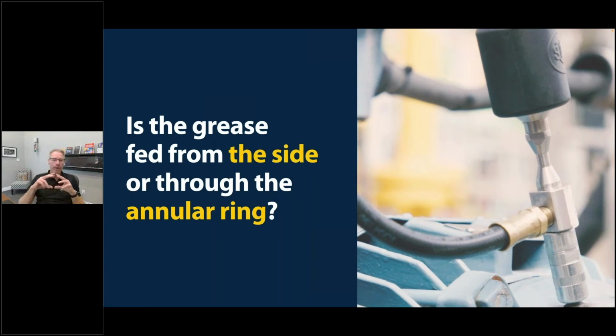The physical fact of which direction the grease flows into the bearing impacts the grease replenishment quantity and is a criteria that our lube expert solution asks for. So make sure that the solution that you're buying does ask for an indication of either annular or side replenishment.